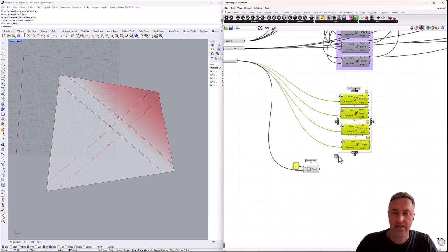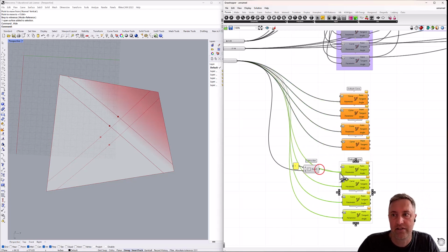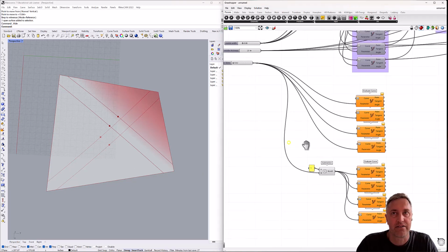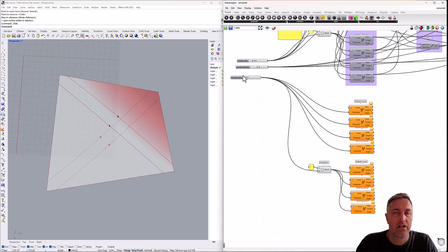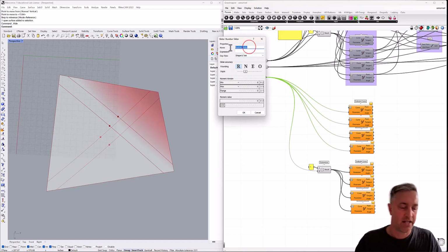We've got those set, and how about we copy all 4? And then swap out the parameter. And we're using 0 to 1 along the length, which is why we're re-parameterizing the curve. So it's not using a dimension, it's using 0 to 1. And this also makes it nice so that whatever our parameter is, we can then subtract that from 1 to get the corresponding other side. Let's call these edge limits.